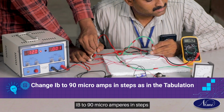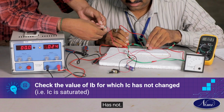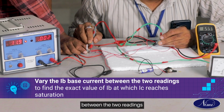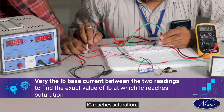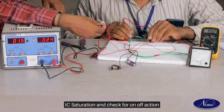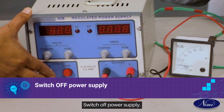Change the IB to 90 microampere in steps as in the tabulation. Check the value of IB for which IC has not changed. That is, IC is saturated. Vary the IB base current between the two readings to find the exact value of IB at which IC reaches saturation. Set the IB to a value just above minimum to cause IC saturation and check for on-off action by operating switch S1. Switch off power supply.